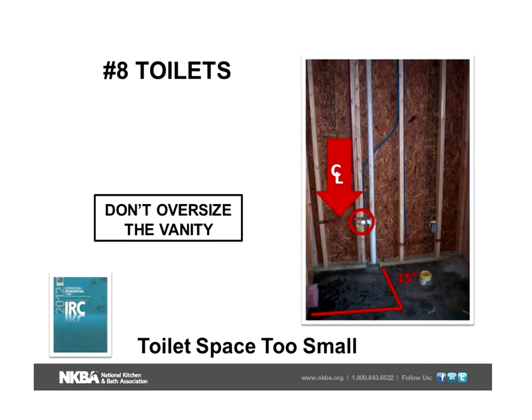Now, here's something else that we run into. We'll go in, we see where the plumbing is, we'll assume the plumber has centerlined the plumbing with the vanity. Not so fast. The plumber actually put it here to keep from probably going over a little bit further or going through an additional stud.